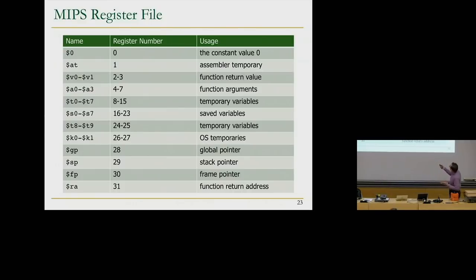There's a temporary register, but the interesting registers are somewhere over here, actually. So you get a lot of interesting registers. Okay, some of these will become more clear when we talk about programming. But you see that there are 32 registers, and they're general purpose, they can be used for anything except for really register 0. Even though they have names over here, you can really use them for anything you want, as long as your program is correct. Except for 0, because clearly you cannot write some value other than 0 to it. By convention, the machine always returns you 0 if you read register 0.